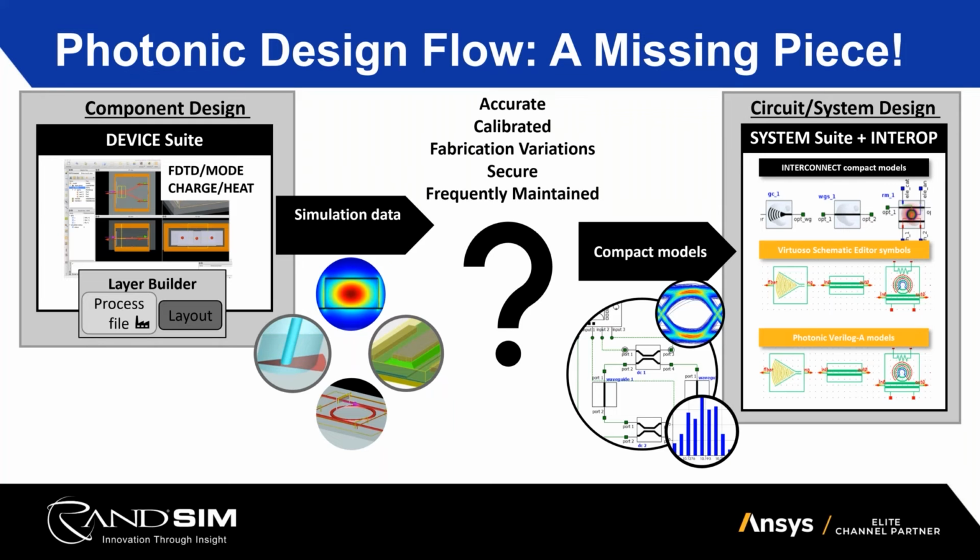For a long time, there has been a gap between the component design and the circuit design. The component designers will design the actual physical component and do its characterization, getting, say, for example, the S parameter, the behavior model, the behavior of the component. But the circuit designer actually cannot get the physical model of the component and usually uses an analytical model or a mathematical model to represent the actual physical model, which is not very accurate.